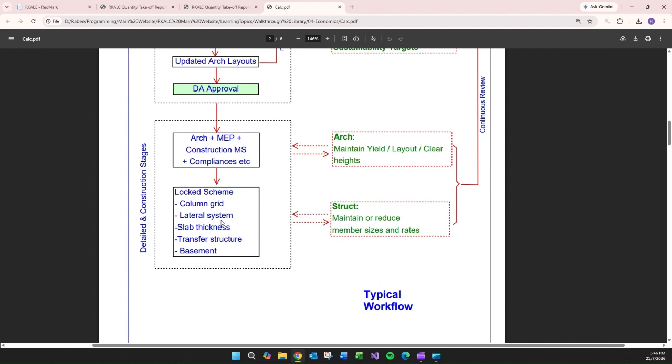So without clarity on those numbers, as an industry expectation ballpark, let's say for PT, 6 kilograms per square meter. With a PT slab, you need something like anywhere between 55 and 65 kilograms per cubic meter and similar. Or if you have a reinforced concrete slab without PT, you're talking about 125 to 135.